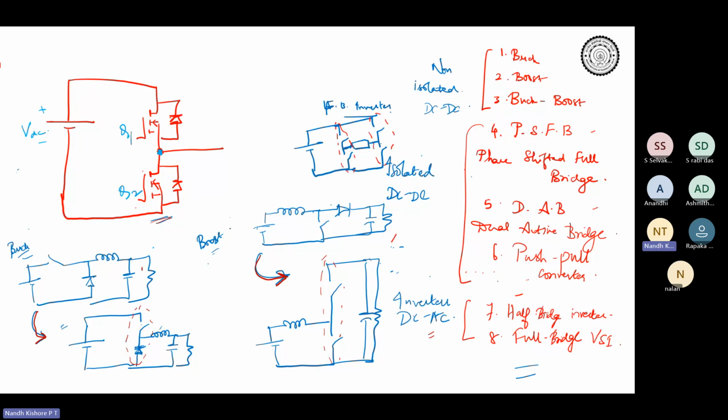So the idea is, if you are able to characterize the devices, the basis of performing a double pulse test is to characterize the devices, that is, to understand how the device operates or functions. If you are able to characterize the devices in a half bridge circuit, as shown over here, you can expect that the device behavior is going to be somewhat similar if the conditions are the same in a power electronic converter as well.